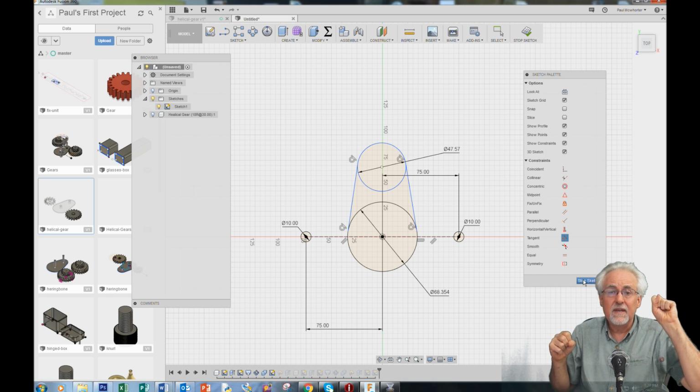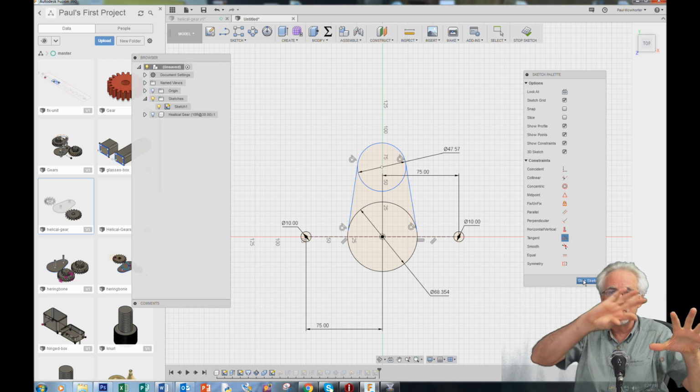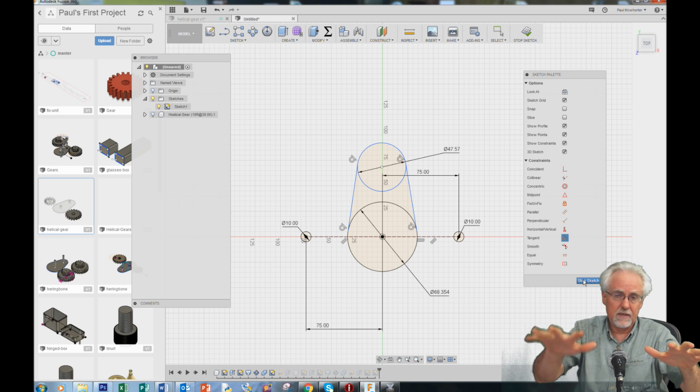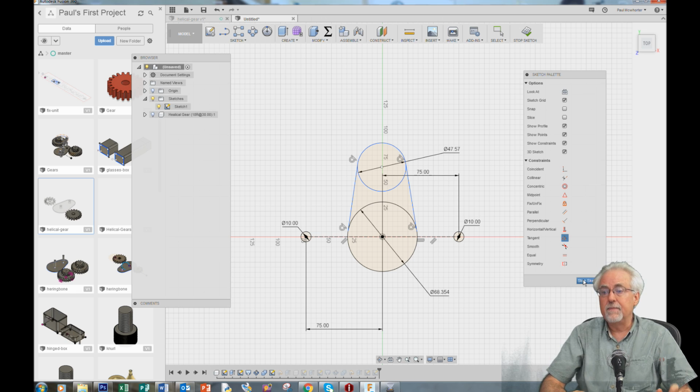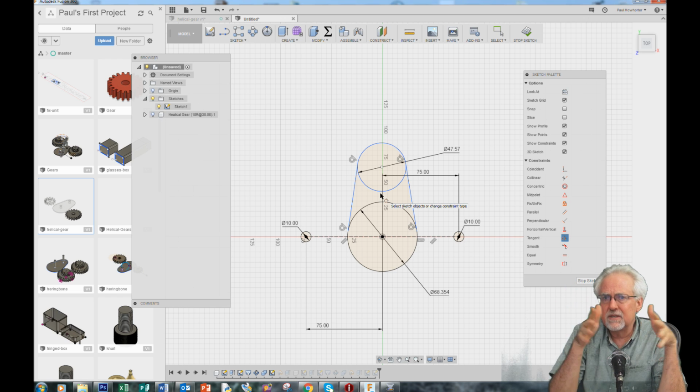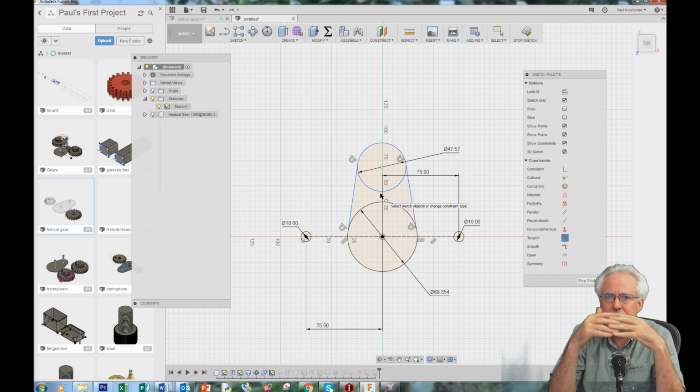You could think of it as inside diameter plus one gear tooth. That would be the same as the inside diameter of one plus the outside diameter of the other. Okay, now divide by 2, because we really want radius now, right? Because I want the distance from here to here to be this outside radius plus this inside radius. If that doesn't make sense, go back and listen to it again, or just watch how gears would mesh. You need the inside radius, one gear tooth, and the inside radius, or the inside radius and the outside radius, and they'll mesh.